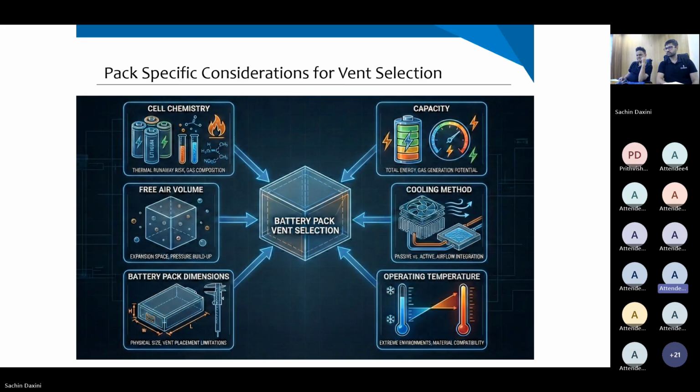Is there any specific reason all these vents are made to burst at that specific pressure, or is it a general requirement? Yeah, so usually our vents would be somewhere between 100 millibar to 500 millibar, depending on the size of the vent. That's the usual range.